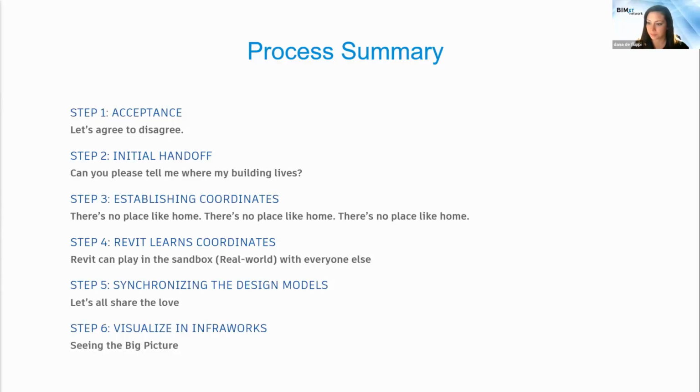How much easier does it become to have a shared coordinate system in a campus environment and share that with your contractors for that campus? Before I fully understood this personally, that is one reason I used to think you'd have to have a local point that you would use. And that's where moving the project base point away from the internal origin might make sense.